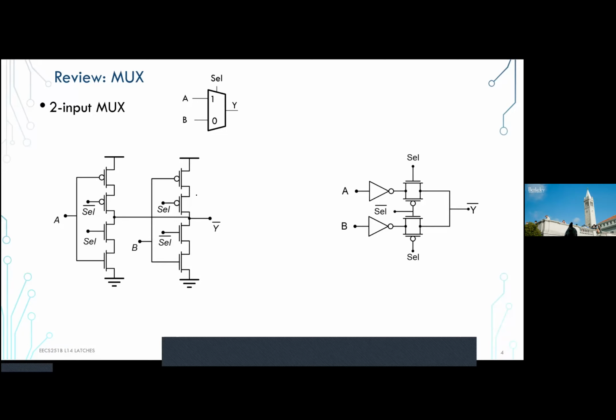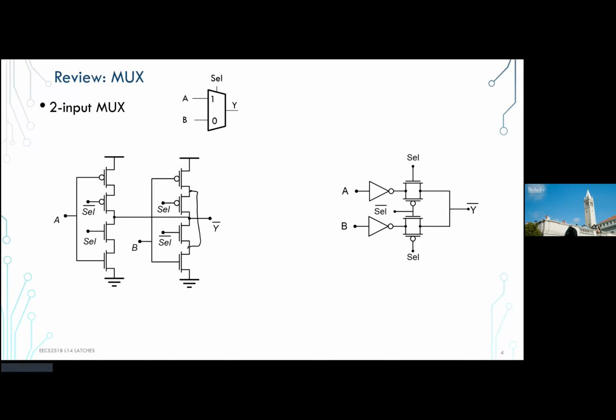If I put a line and connect these 2, those 2 are identical. So the difference between the 2 is just the wire from the stack node on top to the stack node on the bottom. Is there a difference in logical effort between the 2?